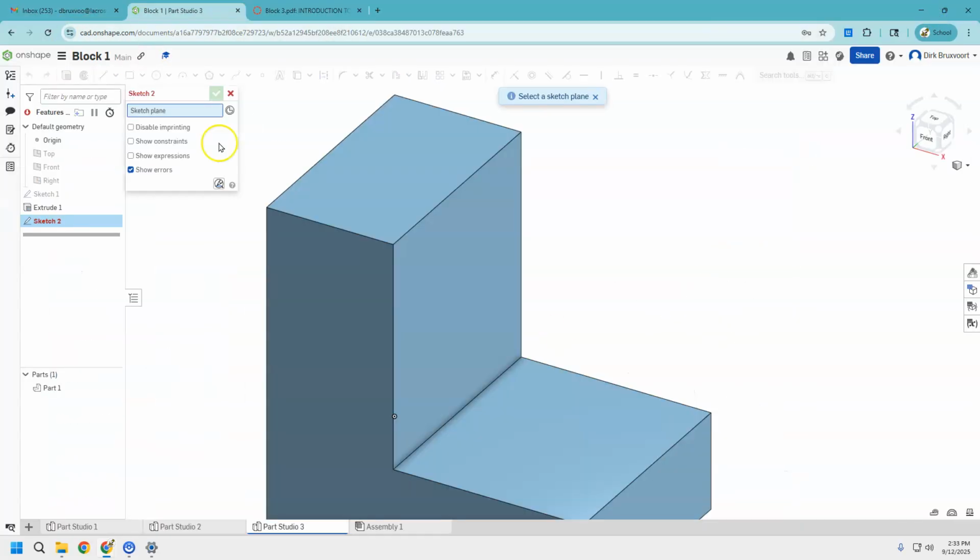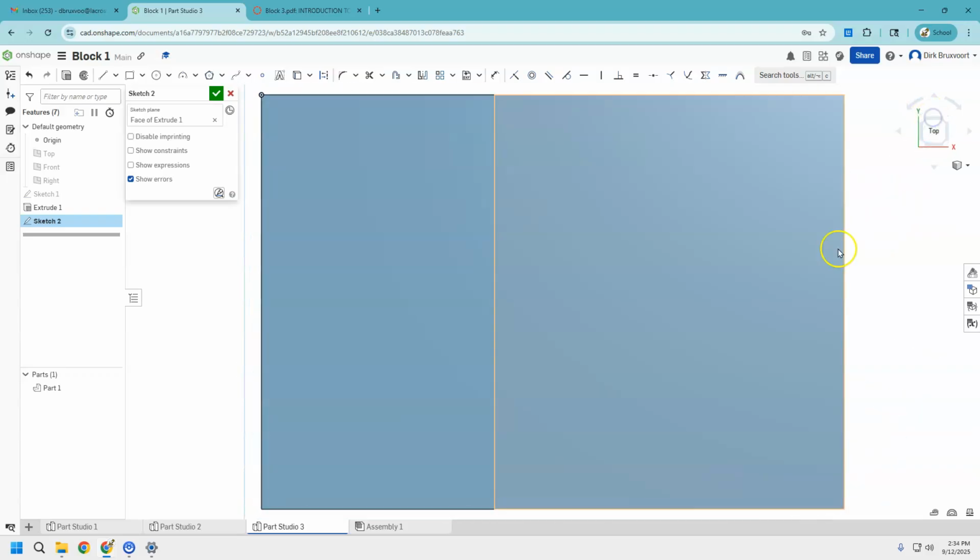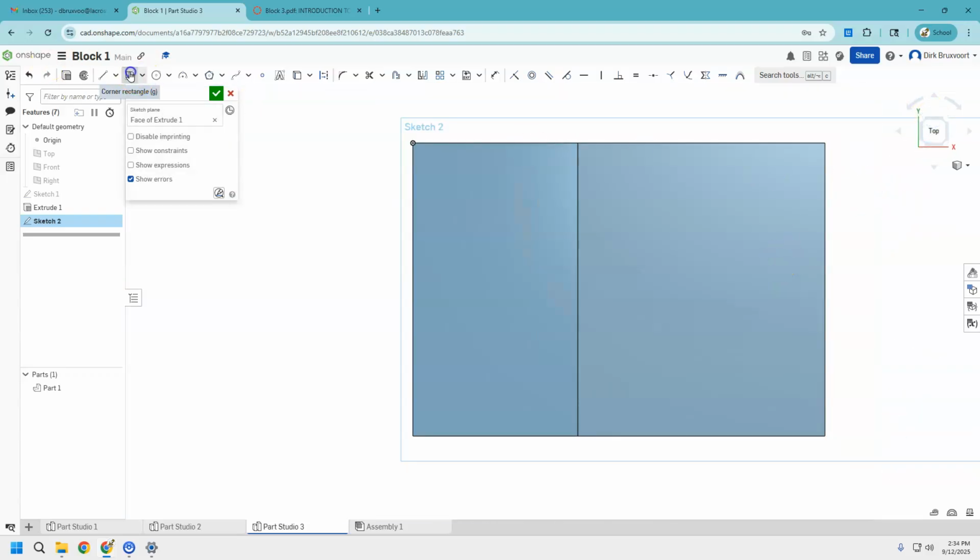So we're going to take our drawing. I hit sketch. There is no sketch plane. I'm going to select right here. It's going to make a sketch plane over that. I'm going to flip to the top, so I'm in a 2-dimensional view right at the top. I'll use my rectangle, and when I draw, one thing I'm going to do here is, if there's a center point, I don't want to be in the center point, because then I'll lock it in. We want to dimension this later.